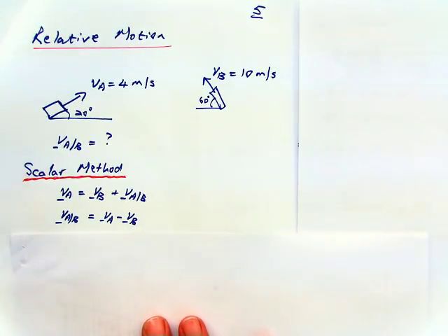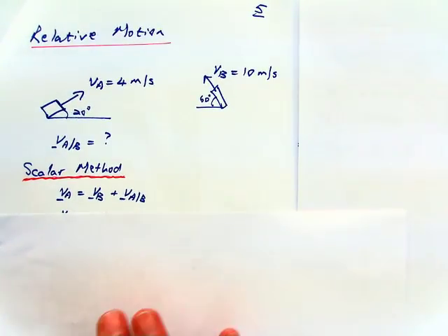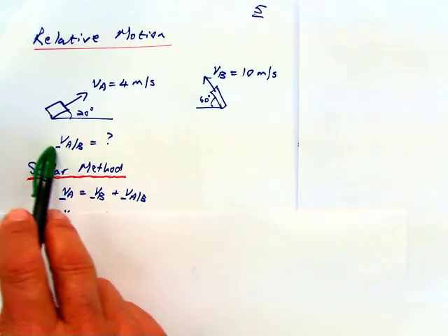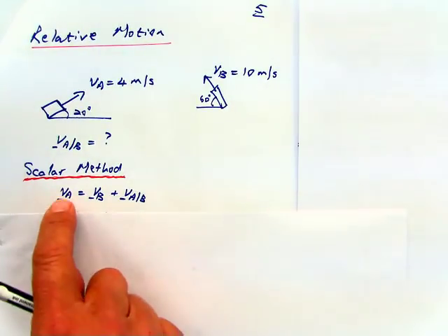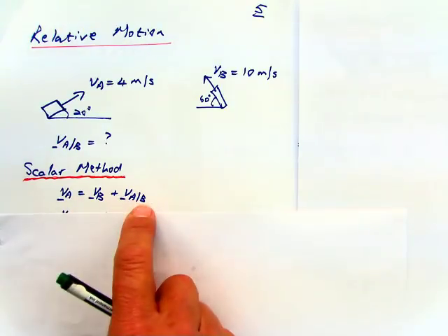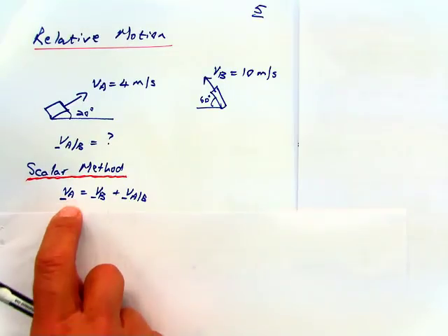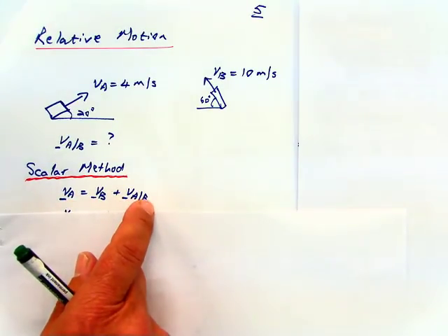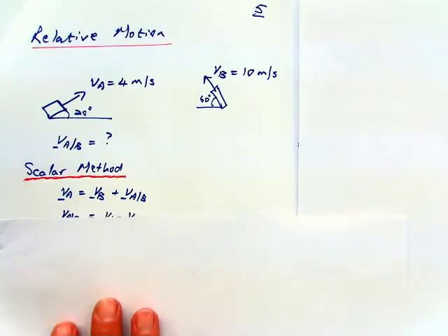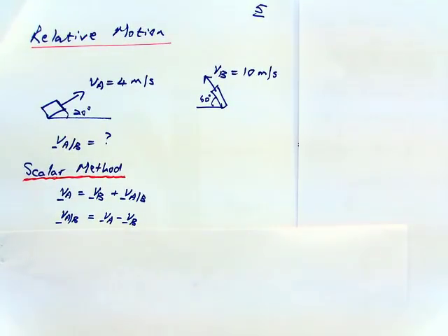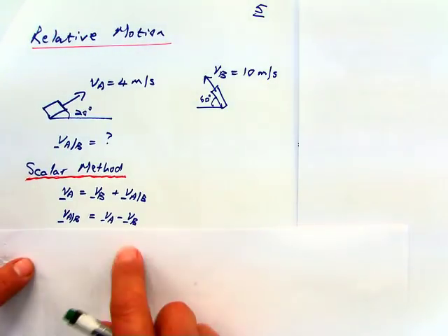And you say, okay, now there are two ways of approaching this. They want the velocity of A relative to B. Now, you can get it from this equation. Velocity of A, when you have an A on the left-hand side, you have A, B, A, B. So it's easy to remember. So when you want that, you need the velocity of A minus the velocity of B.